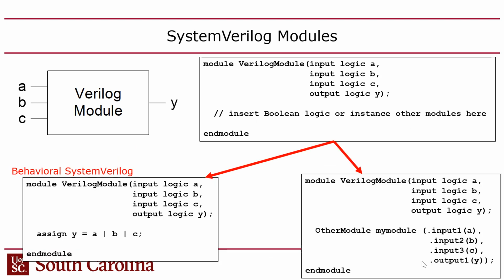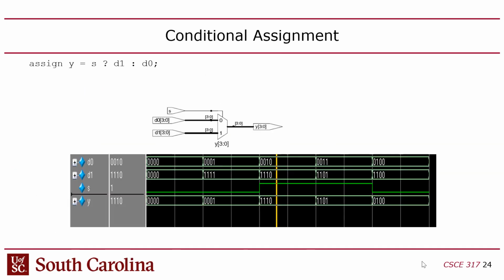Okay, so we talked about modules, and we talked about simulating, but you never got a chance to do this in this class, though I think most of you took 611, so you have done it there. Instead, we used JTAG. You were supposed to use Signal Tap, which allows you to debug live designs. I don't know how many of you actually did it, but I showed you how. I think it's nice to be able to do that. The problem is, you do it and then you want to add another probe, and you have to recompile. That's a problem.